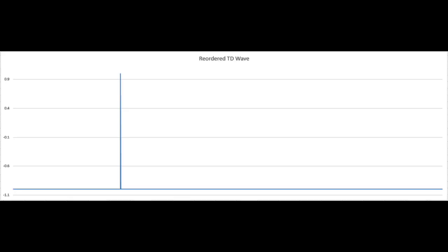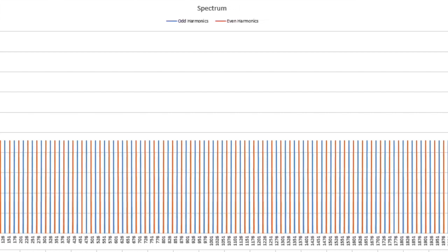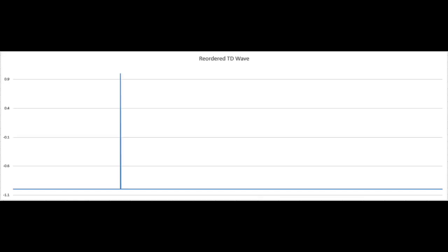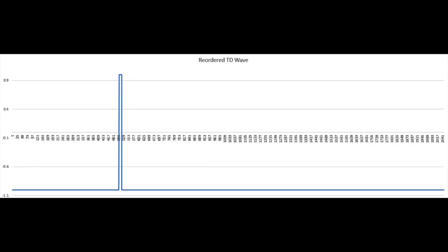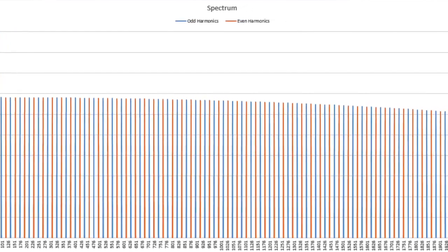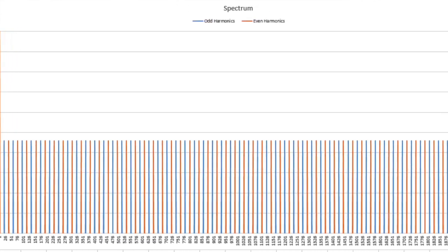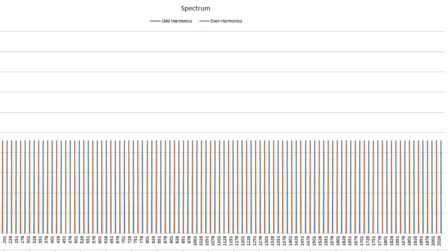I told you how an impulse can't be used to test a filter, even though it has an absolutely flat response. The problem is that the impulse is very narrow, and if you try to make it wider, it slopes off in the frequency domain. And if you're trying to test a filter, that's the last thing you want. You want absolutely flat response all the way to the F max. The thing is that an impulse has to have all the harmonics, or it's not an impulse.